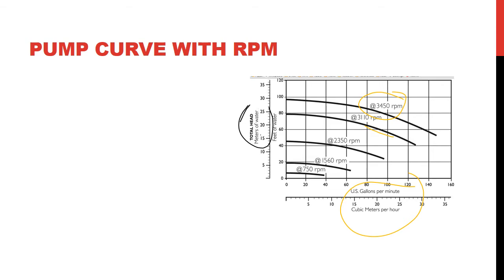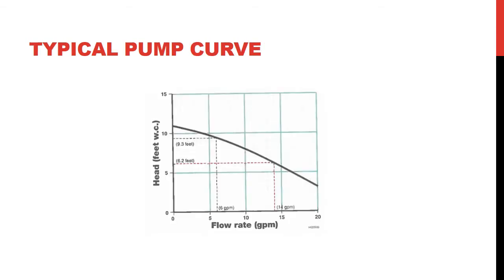And usually you can change the efficiency by going to a different RPM, but this is what will happen. The efficiency will change based on the RPM, and there should be a percentage here at that point. The pump curve here, so head of water, and this is the pump curve. You want to maintain your pump operation around that pump curve in terms of head and flow rate. So we do understand now something about the pump curve, if you heard about it. So you know the pump curve and how that pump compares, and probably that will affect the price of that pump and how it performs.